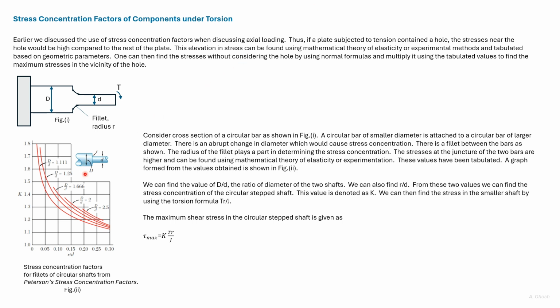The stress concentration depends on two geometric ratios. The first one is big D divided by small d, that is the ratio of the diameters. And the second one is the radius of the fillet divided by small d, the diameter of the portion with the smaller radius.